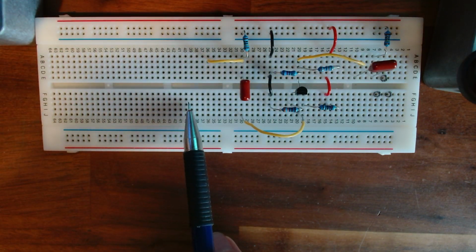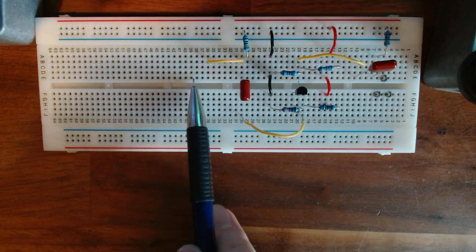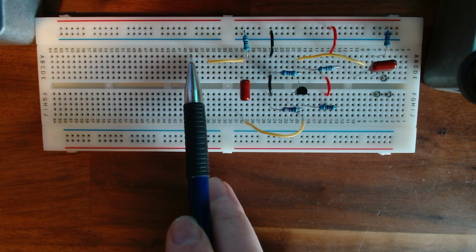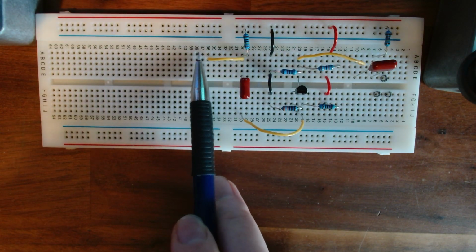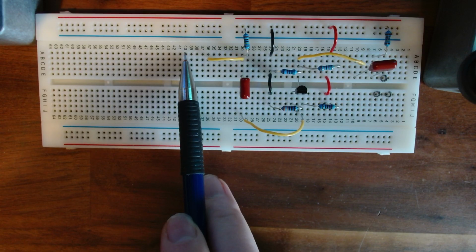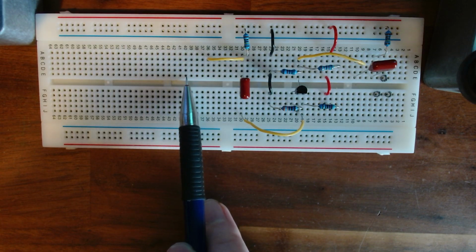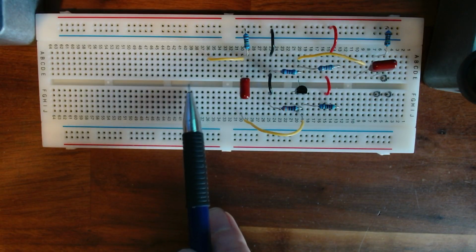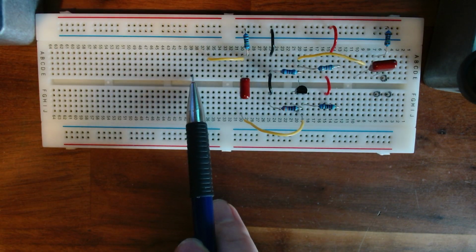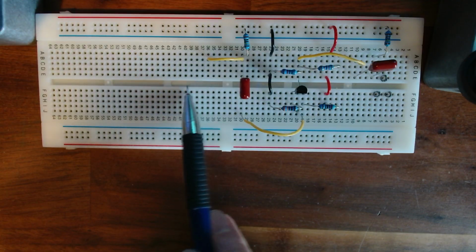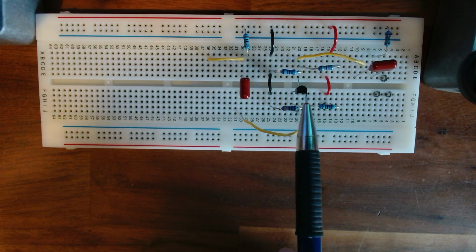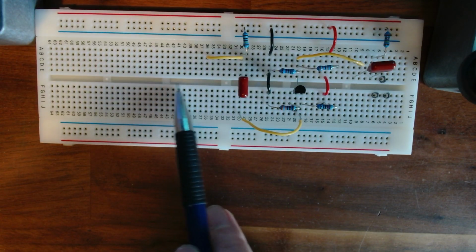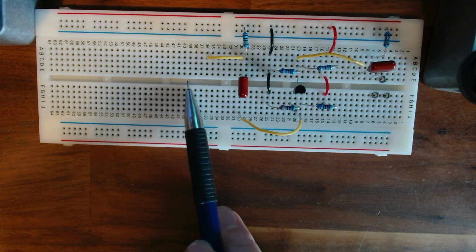These holes in the middle, they run the opposite direction across, up and down the board here, and they're divided into lines here with the numbers, if you can see, so you can keep track of where your component leads are plugged into. There's also this trench in the middle. This is for if you're using op amps and things that don't want one side connected to the other. We're not going to worry too much about this. I've used it a little bit with the transistor just to separate things out, but this is more for using different components.